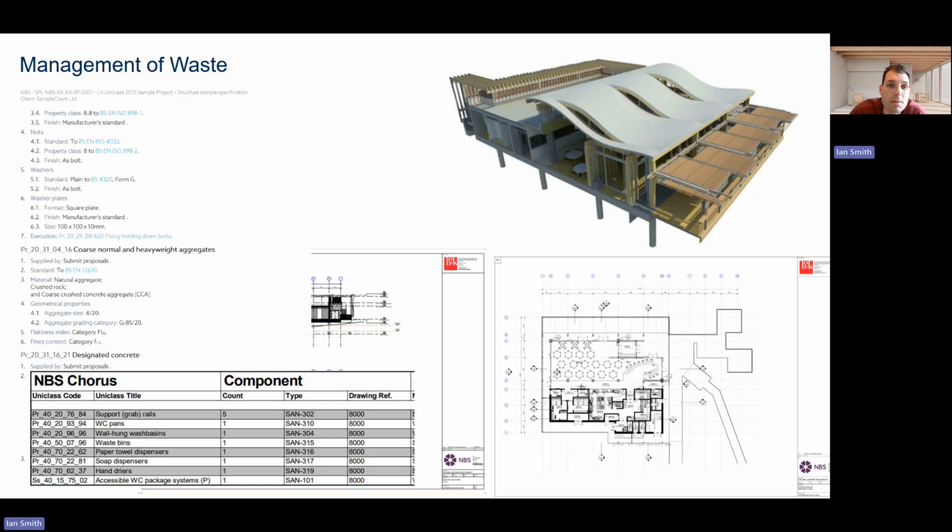One of the key areas where we can manage waste effectively goes back to the beginning, which is optimising the use of materials and making sure our materials are used efficiently from the start of the project. This can be achieved, as we saw early on through the project, through accurate ordering based on our drawings, schedules and quantity takeoffs and BIM models, as well as using prefabricated components such as our SIPs panels that we are using on this project wherever possible.